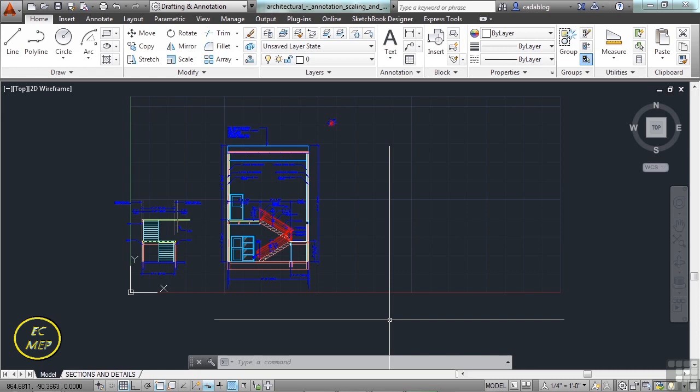Once you're done working in your file, you've submitted it, you've printed it, it's done, and odds are you're not going to work on it anymore, that's a good time to purge. Or if you're going to email a file to somebody, that's another good time to purge your file. Otherwise, I suggest waiting until you're done to purge the file, unless it's just way too big and you need the space, because you never know when you're going to need that extra layer.